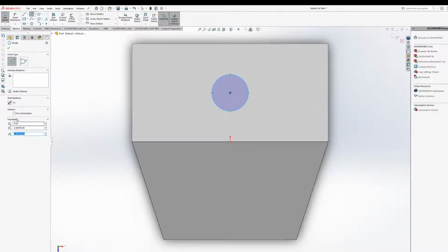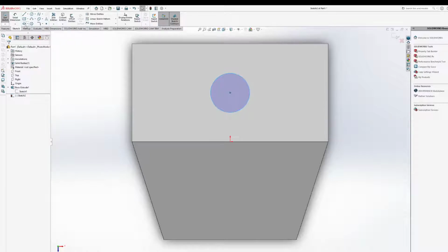What's nice is that on this left-hand side with the parameters, it is already indicating, hey, this might not be the radius that you're actually trying to create. Would you like to indicate something else? So let's say I want it to just be 2 millimeters. I'll do 2 millimeters, and it will already set it to that. And then I'll just hit our check mark, our OK button.